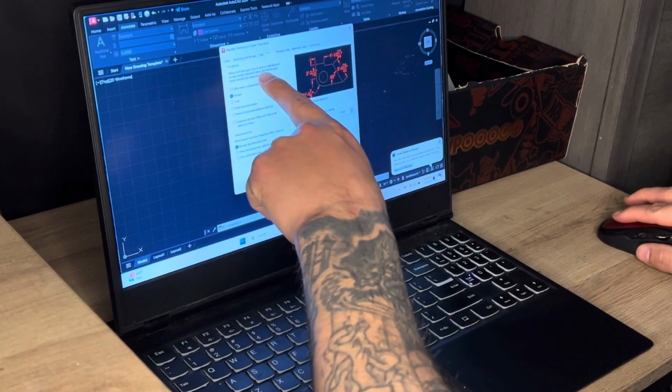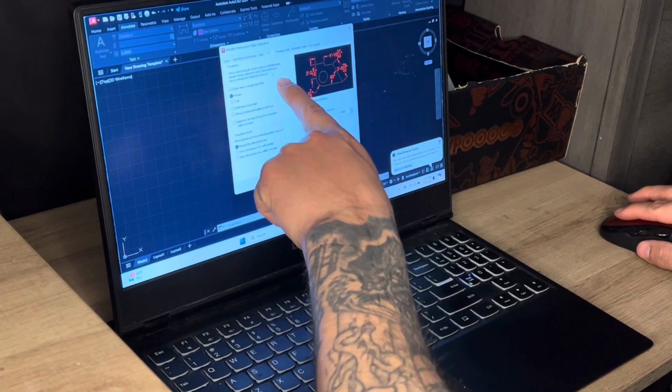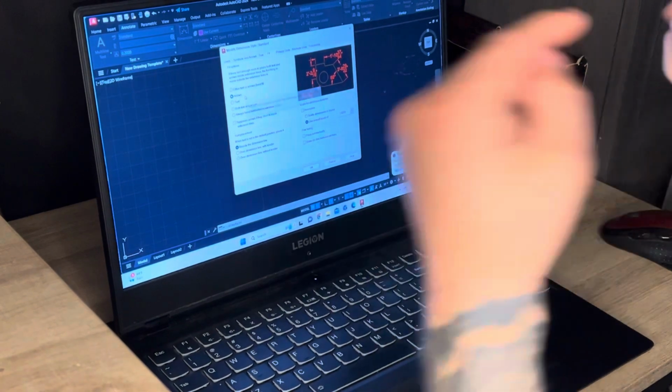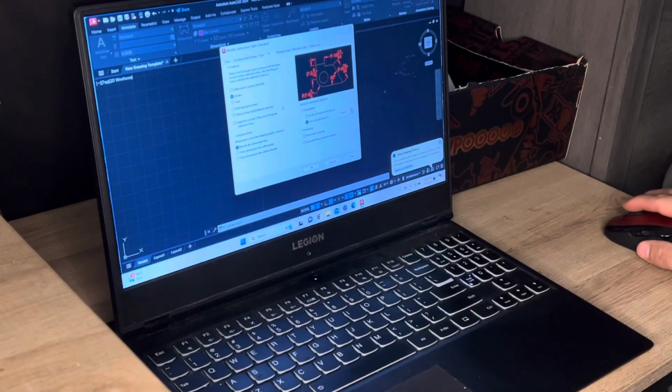If there isn't enough room to place both text and arrows inside extension lines, the first thing to move outside of the extension lines is, and I want my arrows to move, I want my numbers to be inside of my dimension lines whenever possible.